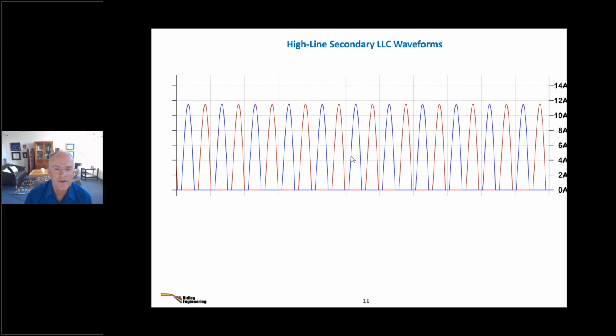Does LLC design fit for high voltage? Yes, it does, because you get nice clamps on those output devices. So it's actually very useful for high voltage. Remember, my first design was a 6,000 volt output, and we didn't use multipliers. We needed an AC output, so it's straight through the transformer to 6,000. LLC, you can use it for wide input range, but the peak stresses down at low line are going to be very high. So it's not necessarily the best choice, and that's why in the industry we don't see it really applied if you've got a narrow range input.